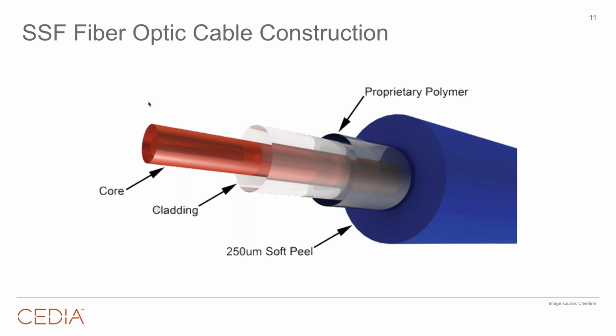These modern fibers, with a polymer coating over this core, allow us to do some incredible things. And it's actually what's known as a bend-insensitive rating, meaning we can take these fibers and literally tie them in knots, okay? Micro bend ratings. You tie them in knots, and they still operate.